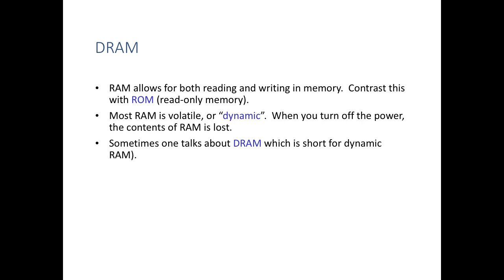The RAM comes in both static RAM and dynamic RAM. The dynamic RAM is volatile, and so is the static RAM. But the dynamic RAM is fabricated using a capacitor, which has a charge that declines as a function of time, whereas the static RAM will retain its memory for as long as power is applied and does not require the so-called refresh that a capacitor needs.